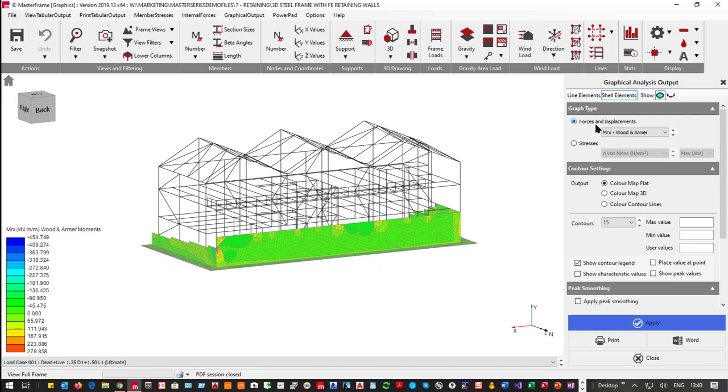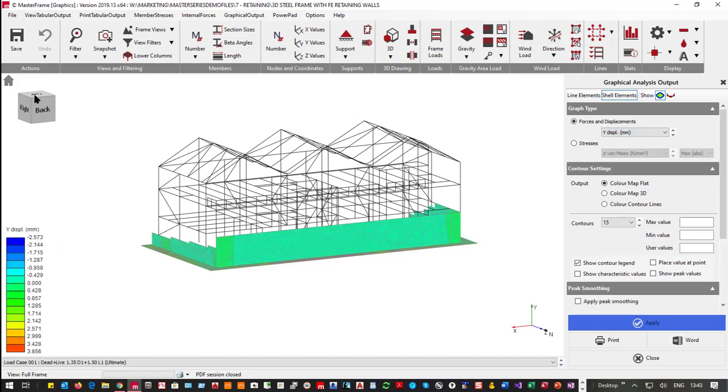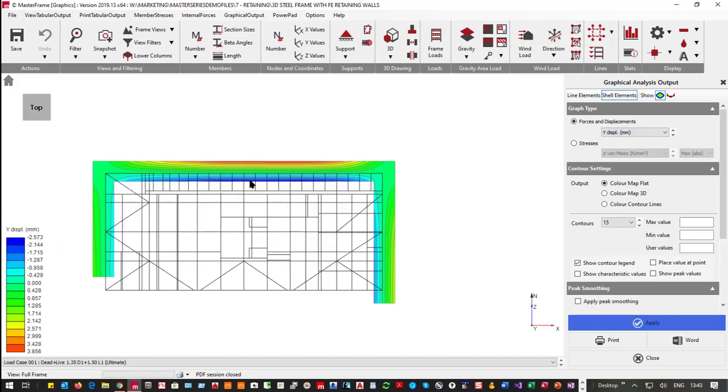But what we're really interested in is first of all the Y displacements, and if I put this on plan, you'll see that the inside is going down and the outside is uplifting, as you would expect. A little bit of rotation because my foundation on my surface, my horizontal surface, had a subgrade modulus with no tensile strength, compression only. So that's going down and up due to the very high wall giving us an overturning, and likewise these are going down and these are just doing nothing much. So a little bit of a down and just a little tiny movement here. So that's quite interesting.